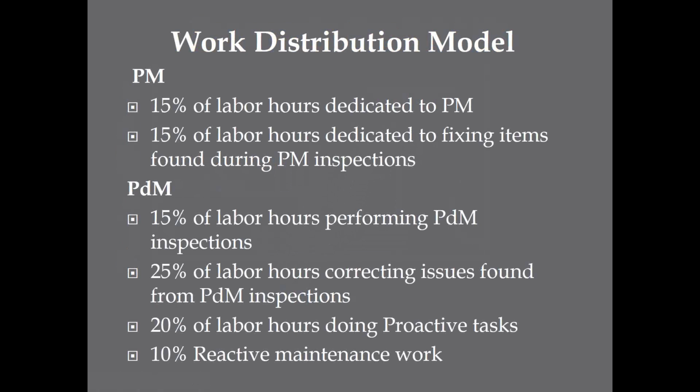PDMs, predictive maintenance. 15% of your labor hours performing PDM inspections. 25% of your labor hours correcting issues found from PDM inspections, which just means we should find more things with PDMs than we do with PMs and put those in the work plans and correct them, tracking that information. 20% of your labor hours doing proactive tasks from that proactive side of the curve. You know, precision alignment, precision balance, precision lubrication, root cause analysis.